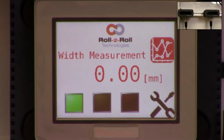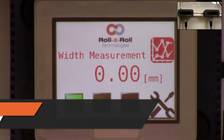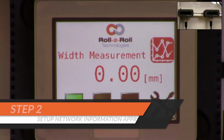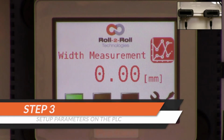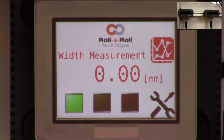The first step in this process is to make sure that we have the SCU5 controller set up for web width measurement mode. The second step is to make sure that the Ethernet settings on the SCU5 controller and the PLC match. And the third step is basically setting up the parameters on the PLC so that you have everything for triggering the stack light as well as data logging. So those are the three main things that we are going to cover.